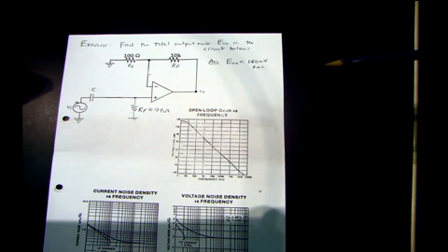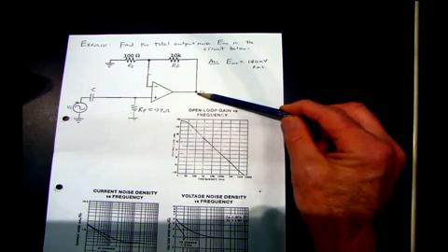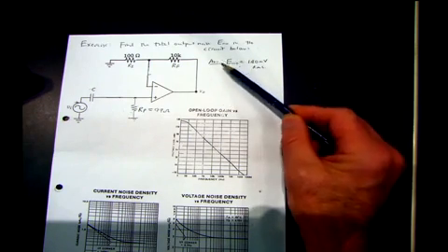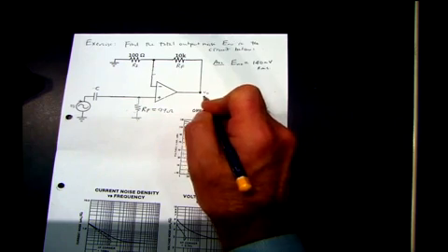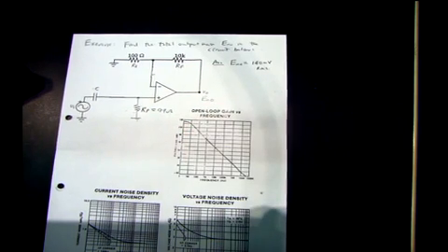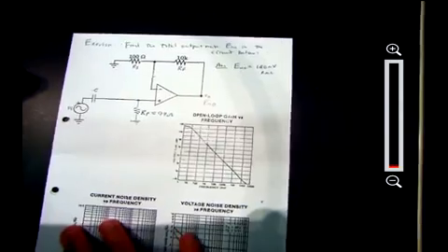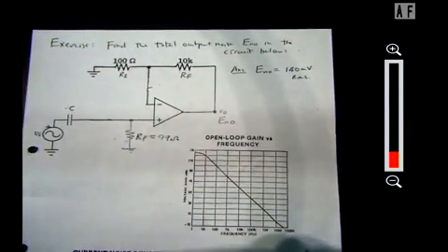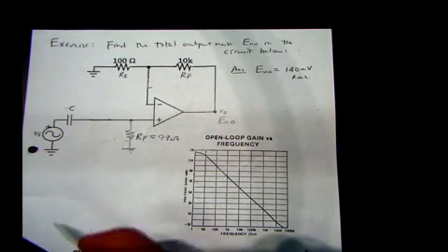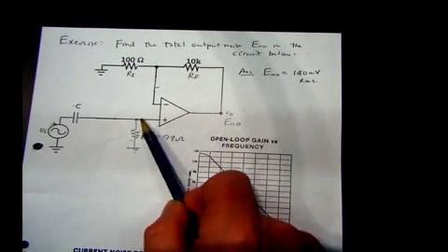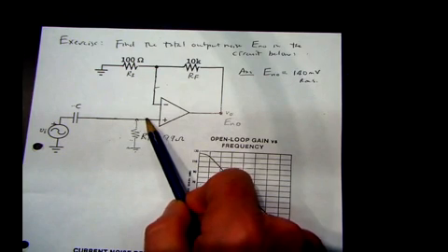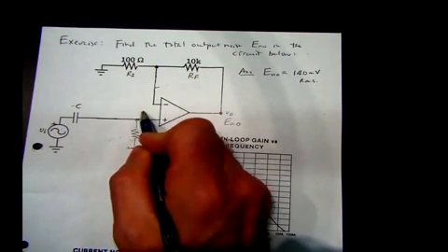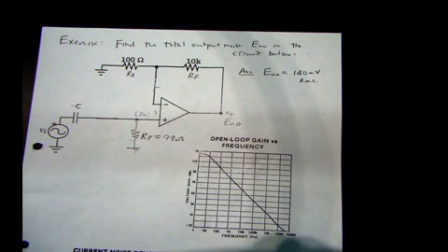140 millivolts RMS is what I calculated for the output noise. That's what we would call noise at the output. And we would get that by modelling the circuit as having an amalgamated noise at the input that I would call E and I over here. We can't really show it on this diagram, but that would be the way I would do it.